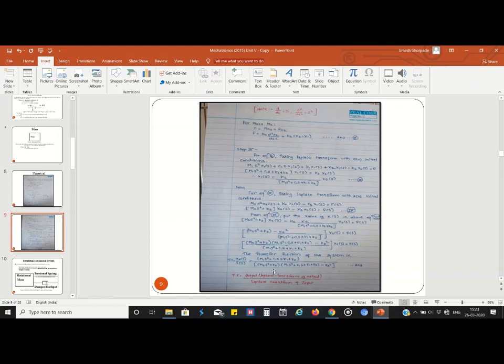So we can simplify this equation. With cross multiplication, (m2 s square plus k2)(m1 s square plus c1 s plus k1 plus k2) minus k2 square, divided by this term. So the transfer function of the system, TF, is equal to X2(s) divided by F(s), the Laplace transform of output to the Laplace transform of input.